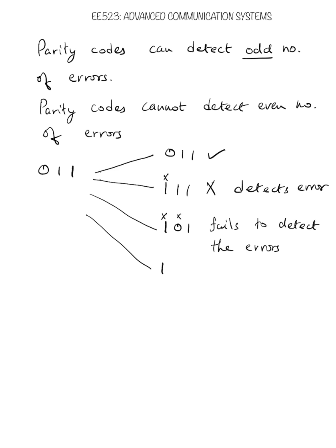And when we introduce 3 errors, let's say the first bit, which is 0, became 1, the second bit, which is 1, became 0, and the third bit, which is a 1, also became 0. So in this case all 3 are erroneous. The receiver can check the number of ones, and it expects it to be even because we used even parity, but in this case there is only 1 one, which is odd. Therefore it detects the error.